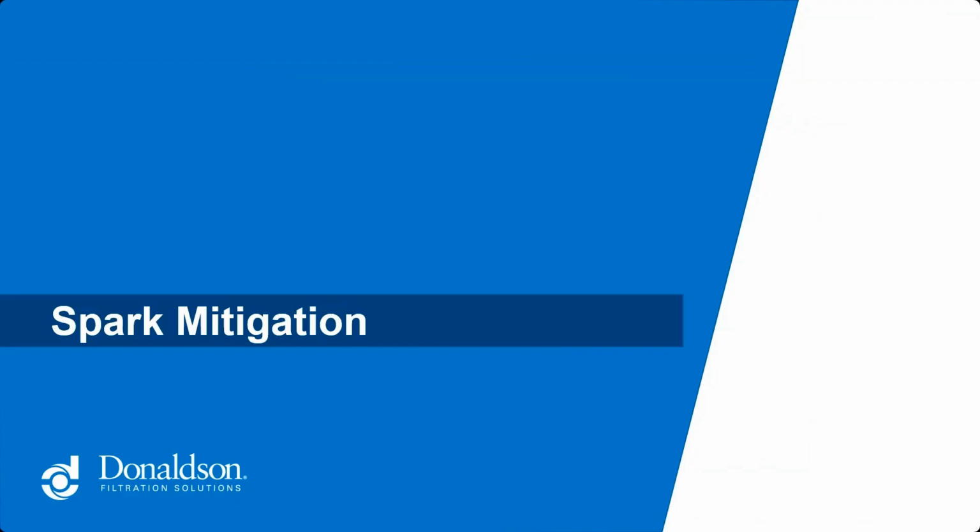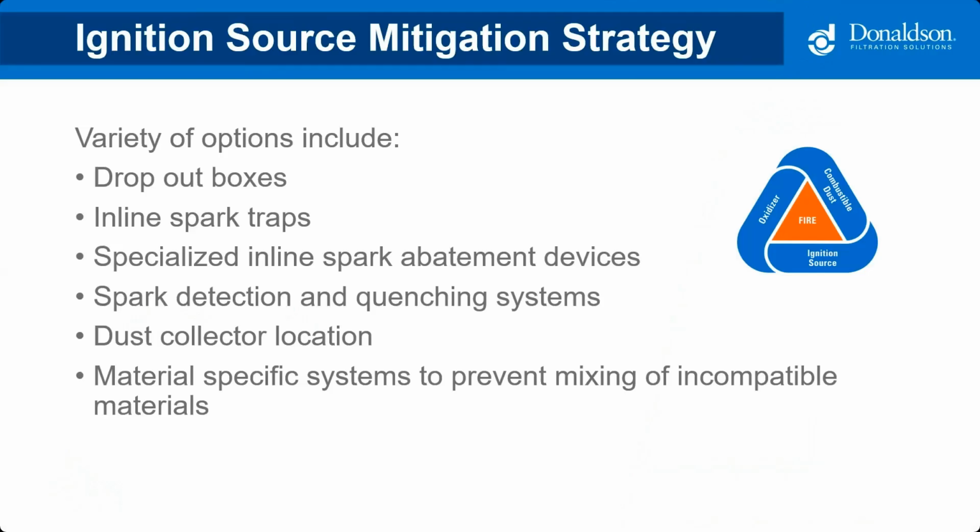All right, so moving on to our next topic, spark mitigation. So since lasers, as mentioned, will generate sparks on the application itself, I wanted to briefly talk about this topic. One method that we can use to help reduce fire risk is an ignition source mitigation strategy. A variety of options do exist, such as dropout boxes, inline spark traps, specialized inline spark abatement devices, spark detection and quenching systems, dust collector location, and material-specific systems to prevent mixing of incompatible materials.